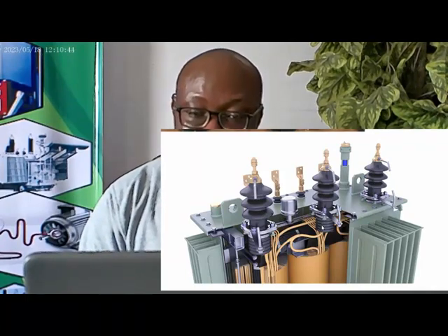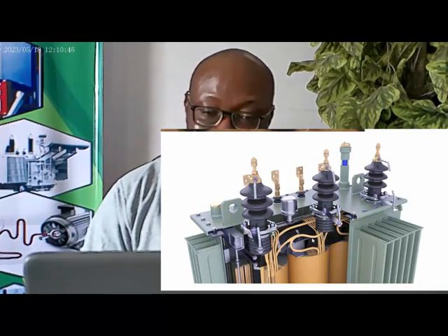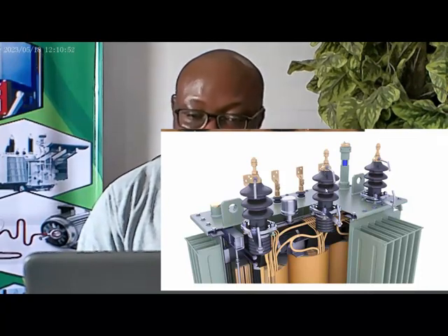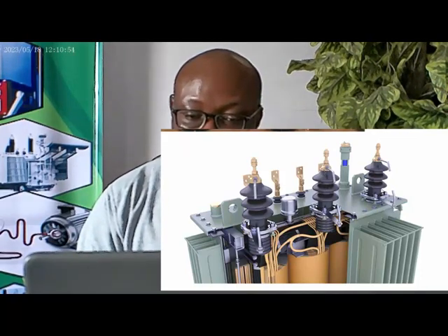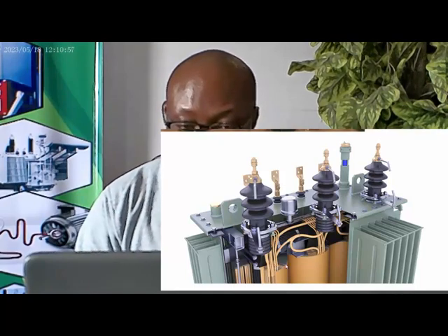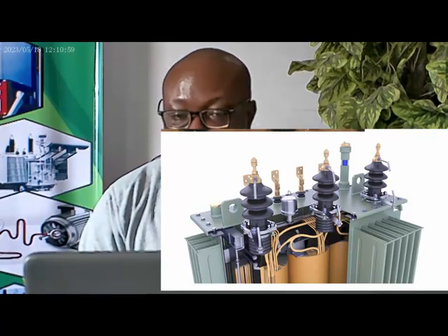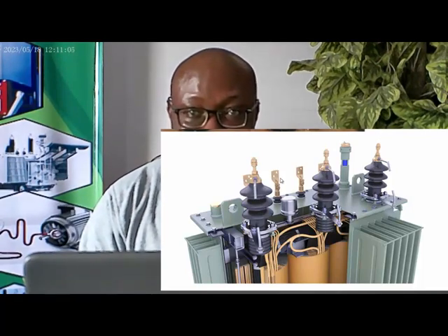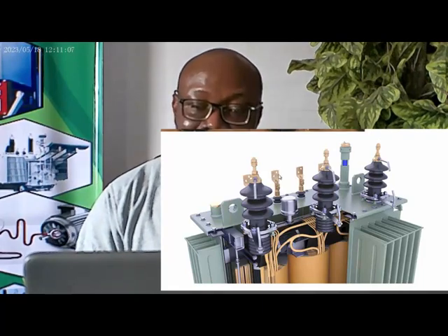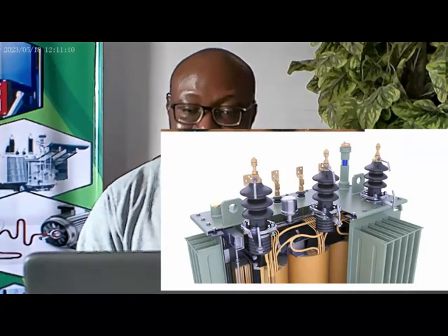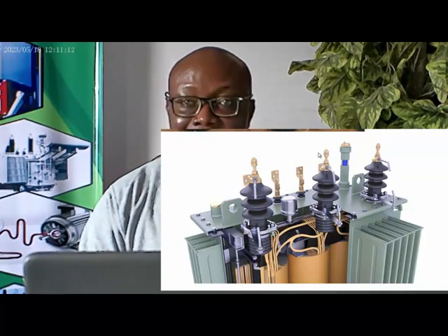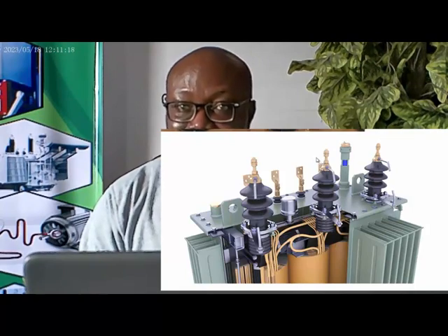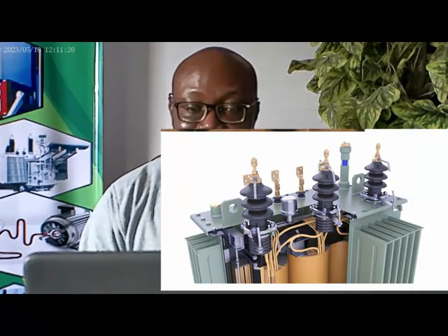So now, when you want to carry out an insulation resistance test or power factor test, as we'll see later, you will see that it depends on the connection. This three-set winding will be delta, as we'll see later. So they have connection; they are connected internally, either star or delta. So this one will read to this and to this because they are connected internally. Then the primary winding has 4 terminals. If you have 4 terminals, that means it's star, as we'll see later. The common or the star point will form the neutral.